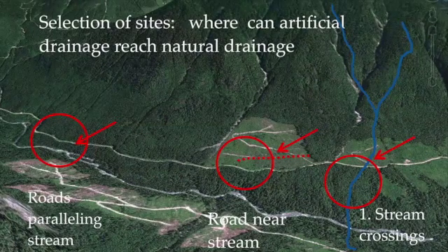If a road parallels closely to a stream, a relief culvert can carry sediment from the road, run over land, and deliver it to the stream. Also, places where there could be a landslide or a switchback somewhere up the road could concentrate enough flow, which could cause formerly subsurface flow to come to the surface and be able to flow to the stream and carry sediment with it.